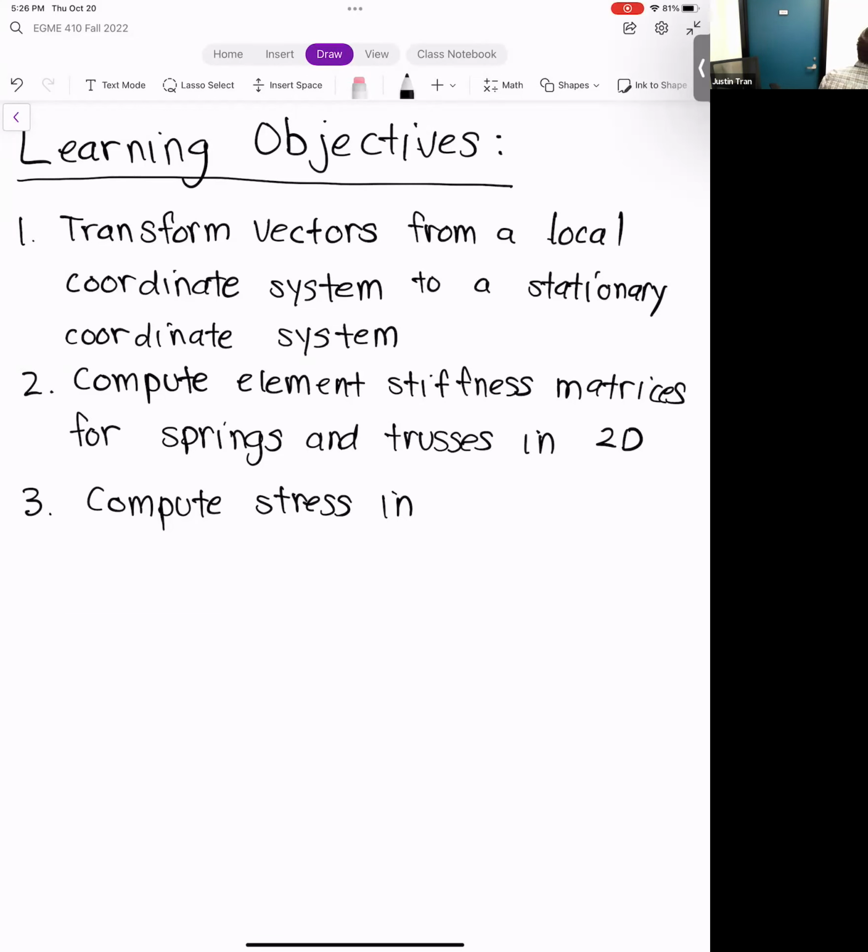So what I did was make this outer edge, I believe, a fixed support, and then add the weight onto here. Yeah, that works too. Then mainly I wanted to analyze these. I put the stress on these, but I want to make sure that I was doing it right, or at least within a reasonable boundary condition. So it's just on this part that's exposed that we fixed it. Yeah, that makes sense.